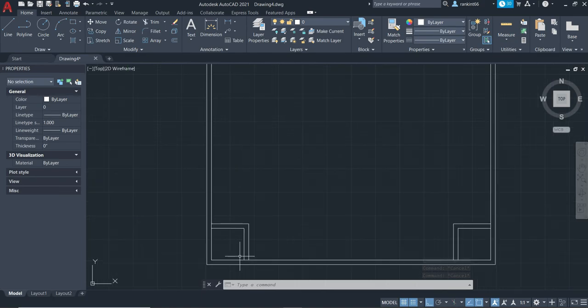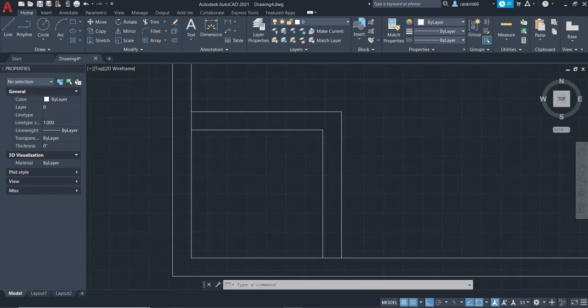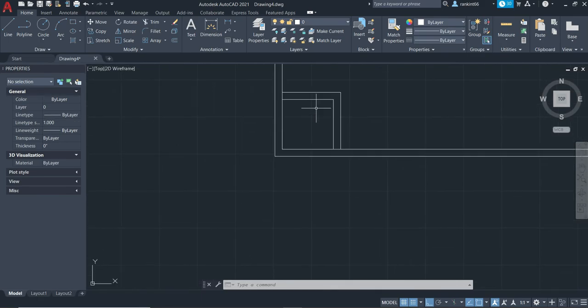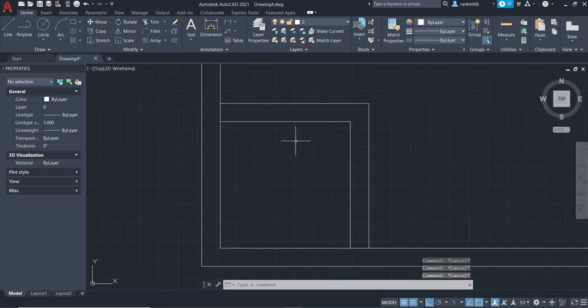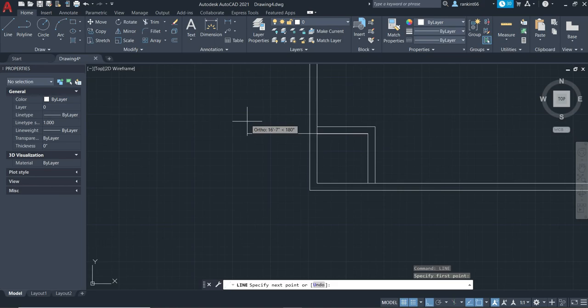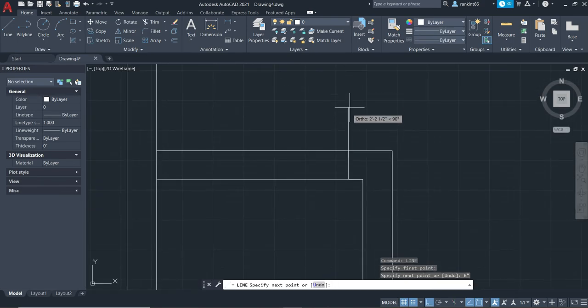Now I want to go ahead and draw the doors in. I'm going to this bottom corner to choose just this first lock to follow through with it. I'm going to choose the line tool. So I'm typing in line, and then hitting enter. Then I'm selecting this bottom corner, and I want to make sure I'm drawing to the left of that. I want to draw over 6 inches. So I'm going to type 6 and then use inches and hit enter. And then I want to draw upwards to get that line across.